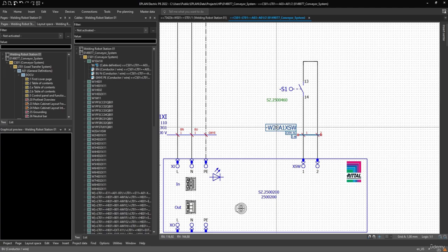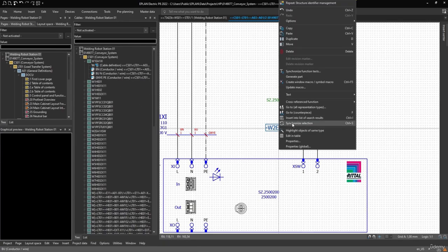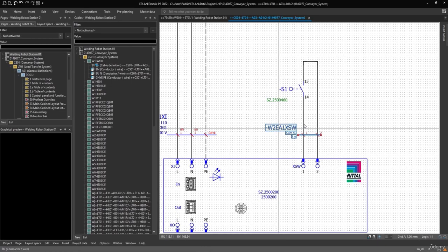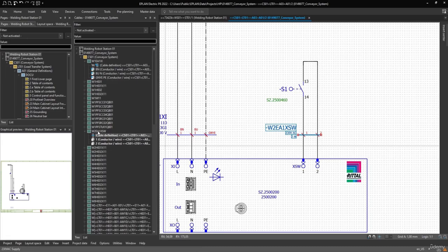You can easily just click on that cable. And with your navigators open, you can just right click and you can synchronize selection. So when you synchronize selection within your cable's navigator, Eplan will synchronize directly to that selected cable. So I'll just click synchronize, and Eplan synchronizes to it. So you can see these ones, they have a cube, but they don't have a triangle. So it could mean that the cable that I have selected here is maybe not in my database. So if I right click on it, let's just see if it's in my database.